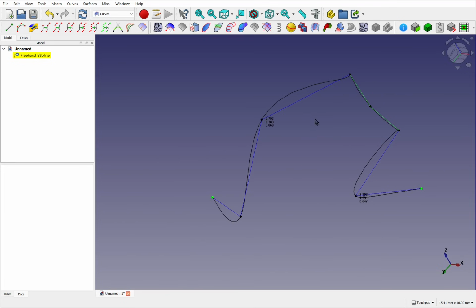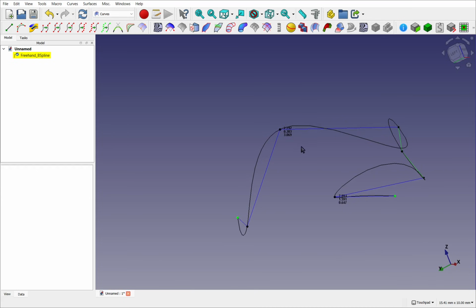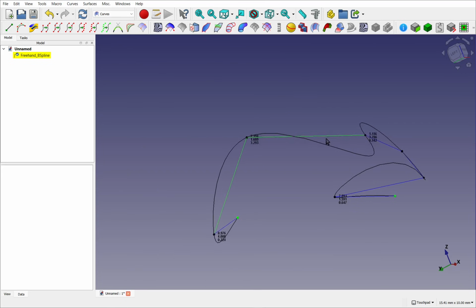Let's now align some segment lines. So I'm going to take this line and control select this line. And then remember, if we start moving the mouse, it will pick those up. So it's best to keep the mouse pointer stationary. If I hit P, that will align those lines. Click to accept. So those are aligned now.